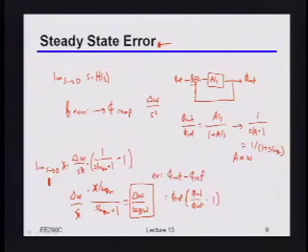So in other words, what this tells you is if you put that ramp into the first order system, that first order CDR, then you're going to end up with a static phase error that's basically proportional to the rate of that ramp relative to the bandwidth of your loop.